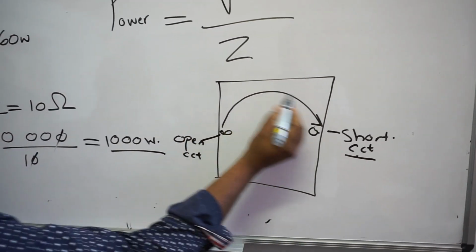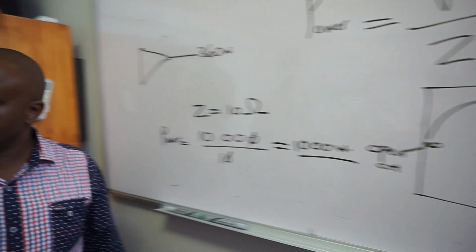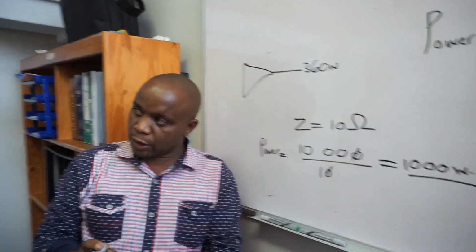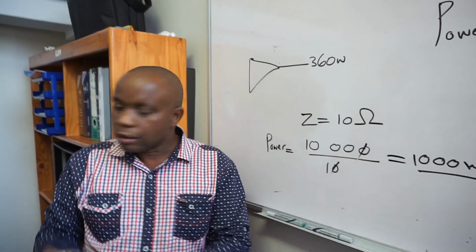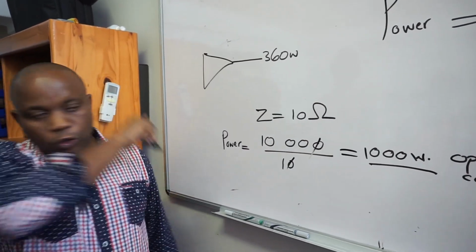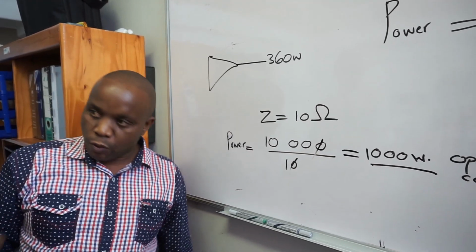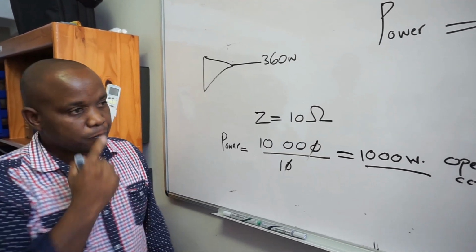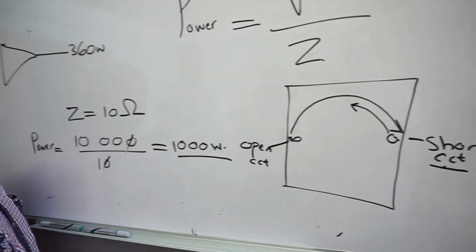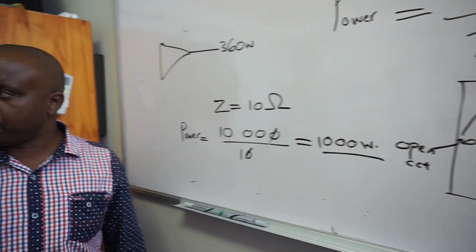So any reading that goes towards 0, you need to double check why it is going towards 0. It's not always going towards 0 because there's a dead short. It can mean that the speaker line has got a long speaker cable run, plus we've got a lot of speakers over there. This is where we come to the speakers now. To move the meter dial back upwards, what do we do? We tap our speakers at a different level.